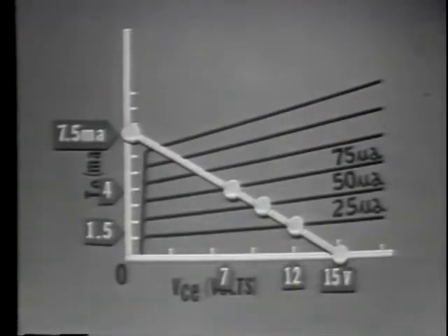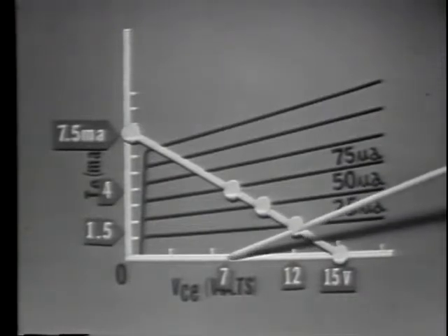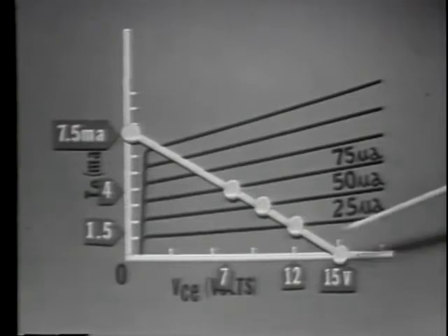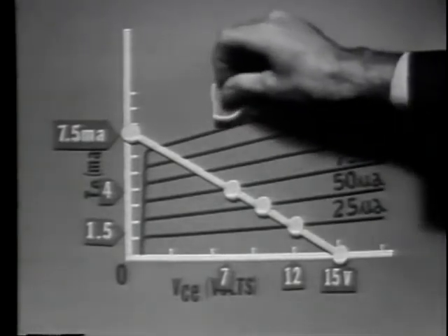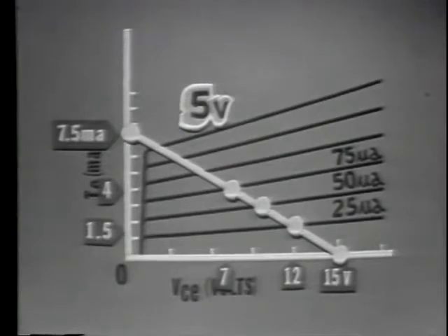At the same time current changed, the graph indicates a collector voltage change from 7 volts to 12 volts, or a total of 5 volts peak to peak. Okay, we have a 5 volt peak to peak change in the output, but what was the input voltage change? Remember we said earlier the base to emitter resistance was 4K ohm. Well, with 4K ohm of resistance and 50 microamps of base current, according to Ohm's law, the input voltage change must be 0.2 volts peak to peak.